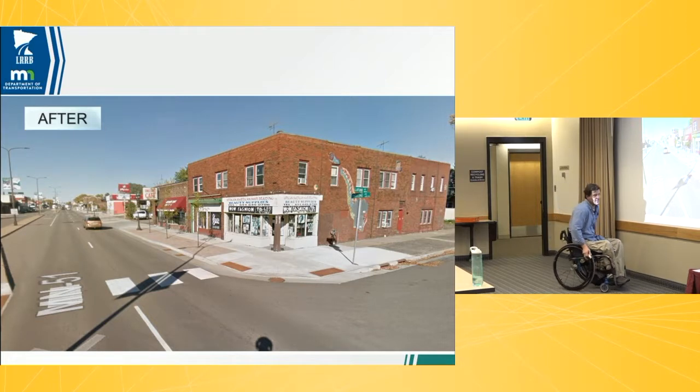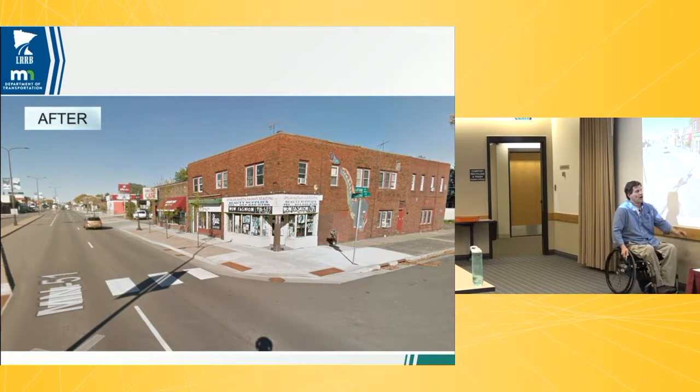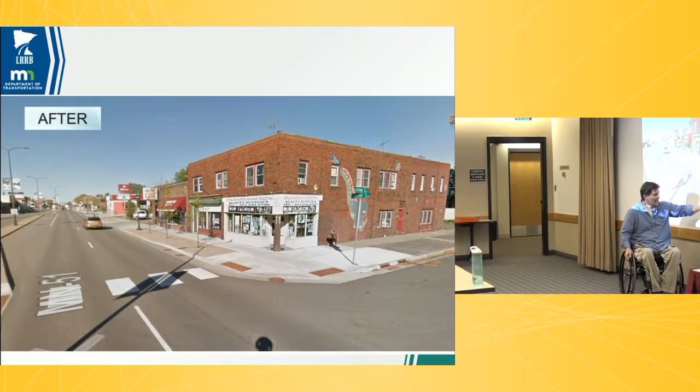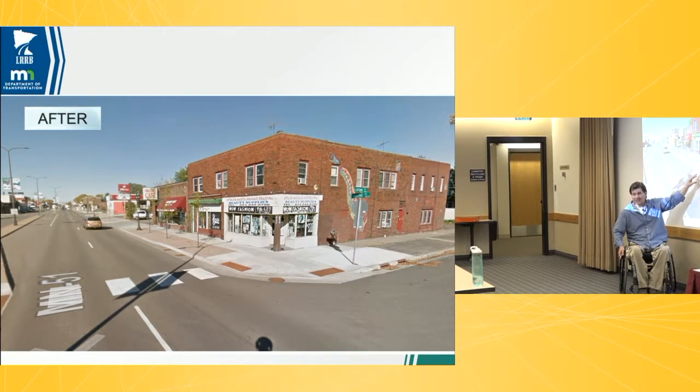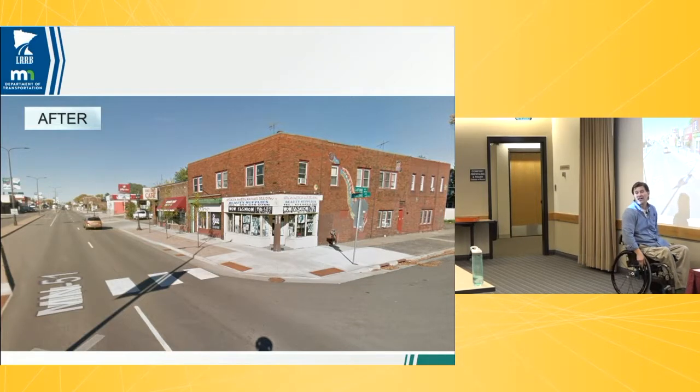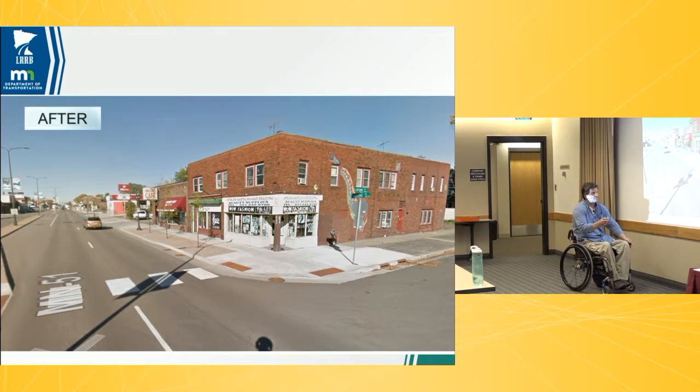And that's one thing I will say about the drainage structures. Often we do not want to chase it back into these types of storm manholes, because that's real money, digging up all this. When I start moving this structure, this one I think we did move, but often we'll just leave that structure in place and add leads on. So that's the shallow depth ones, $5,000 a pop, fairly economical. You start digging them back to the mains and digging a new trench for a new location, that's a lot more dollars and really unnecessary in most cases.